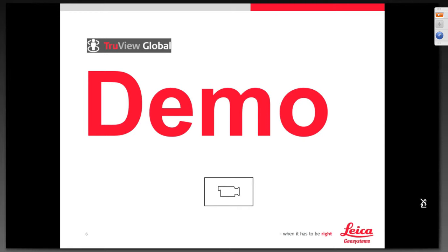Great. Just one more question quickly here, regarding the accuracy of the measurements when you're using the markup tools. Someone was wondering if you were actually going from the center of the bolts to get that accurate measurement. Again, that's a great question. And no, although the data that TruView is getting is survey grade data, using the Leica data or whatever data it comes from, the tools themselves are generic, simplistic tools.